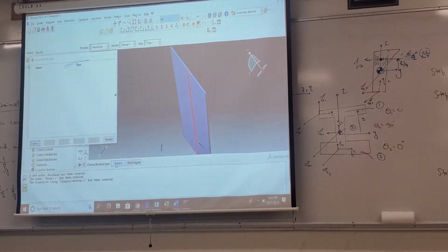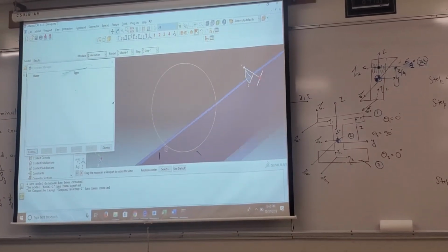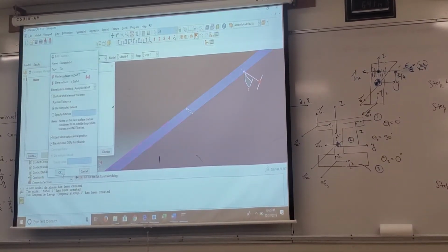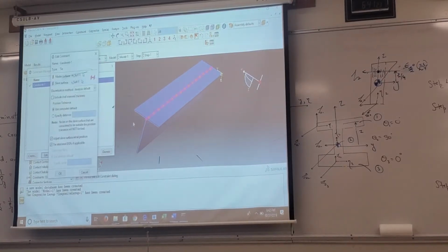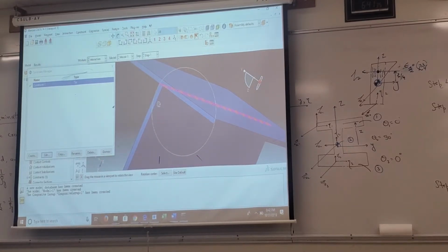And for the slave type, again surface, I will make an invert display option and then select this surface for the web. So once that is done, you will find that all the flanges and webs have been defined. So I will again bring all of the parts together, and when I say edit, you will see that the bonded connections have been defined at the interface. At the interface of the flange and the web, Abaqus now considers that surface as properly bonded.